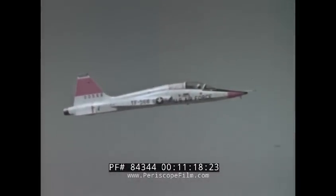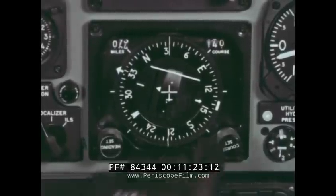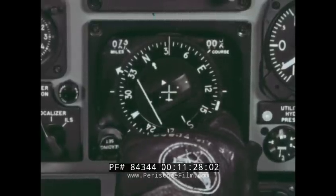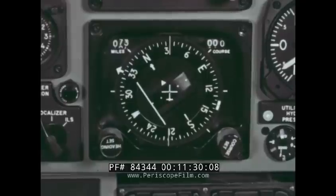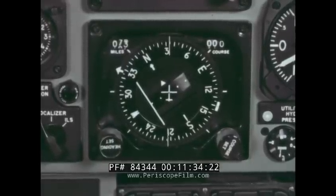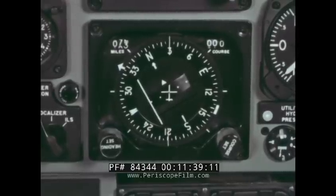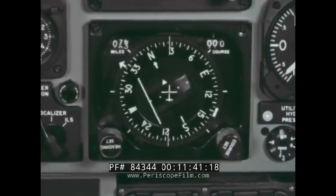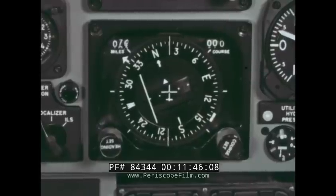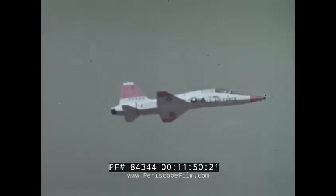Now that you've reached mission altitude, let's intercept the course. Our first reporting fix is Austin. The course is 360 degrees. Set this into the course window. Locate the course you've selected on the compass card. Proceed around the card to the bearing indicator. Any heading beyond the bearing indicator will provide an intercept to the selected course. In this case, we'll go 30 degrees beyond the bearing indicator. This is our intercept heading.